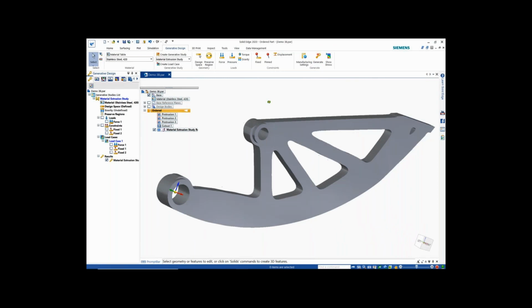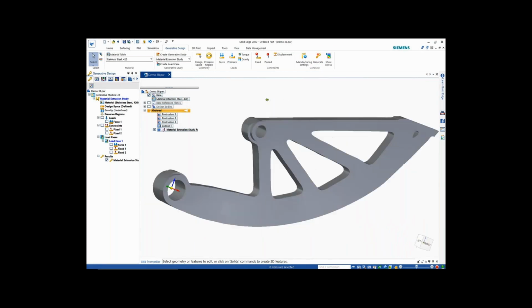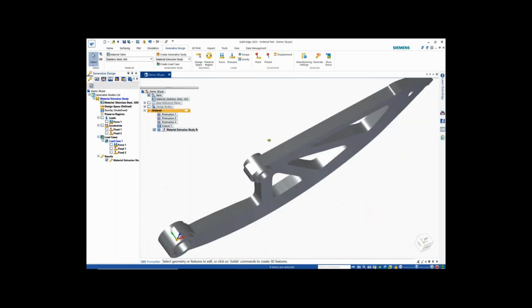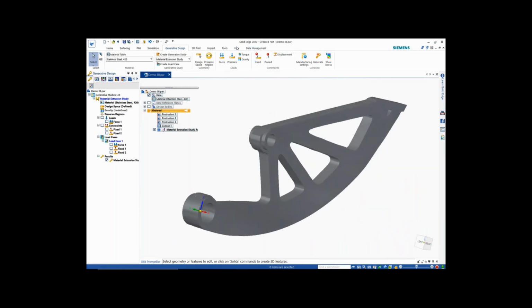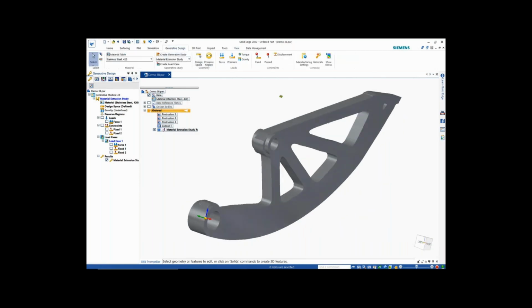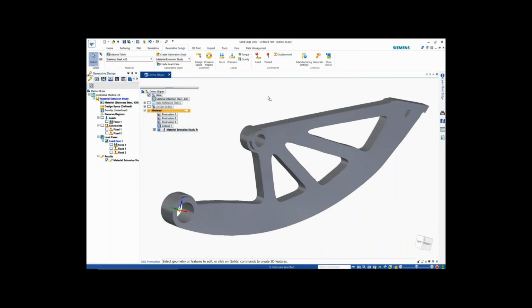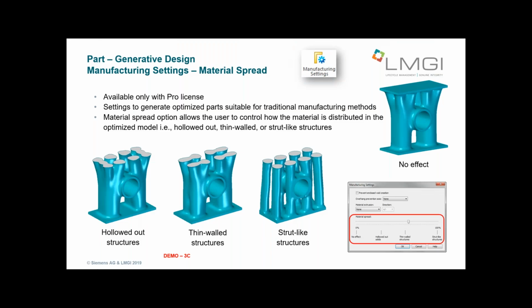So this could be certainly machined with 2 operations on a 3-axis milling machine. So much simpler result using the extrude. I think that should be pretty good.